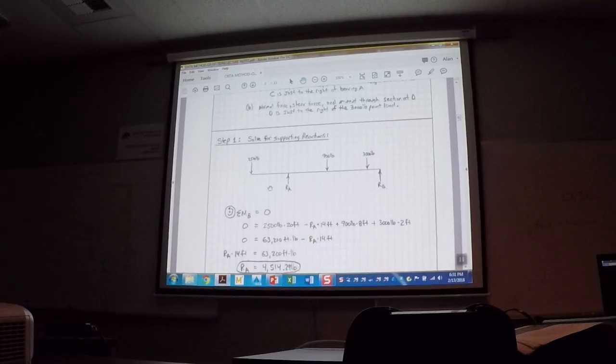So, I wanted to figure out my support at collar A first. And I realized, since I have two unknowns, if I take the moment about B, the reaction at B, if it goes right through it, has a 0 moment arm, so it falls out. So that is one of those things that we can do to take two unknowns and simplify down to just one by taking the moment around where one of them is being applied.